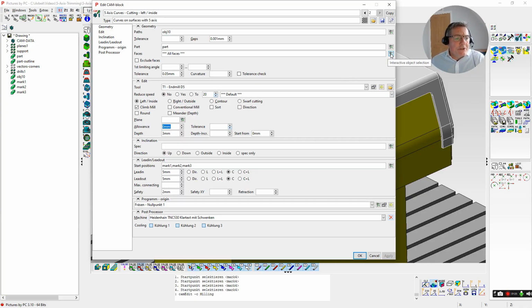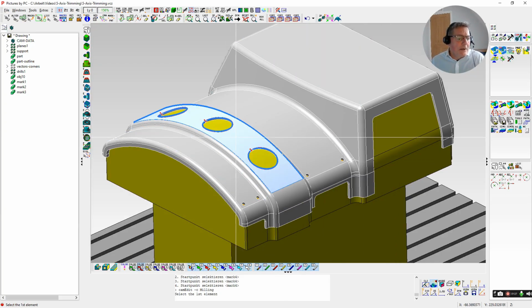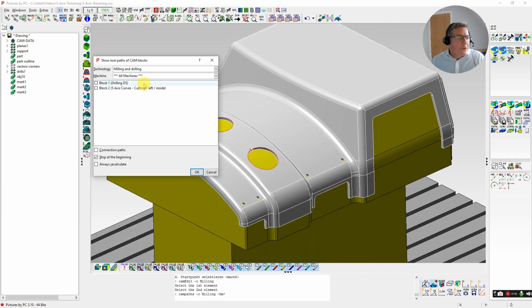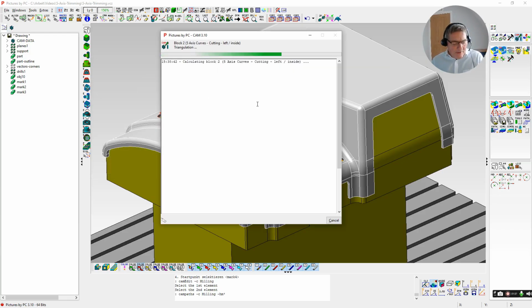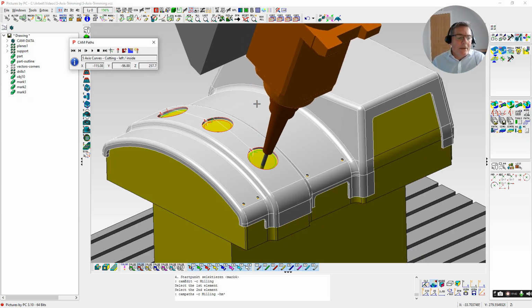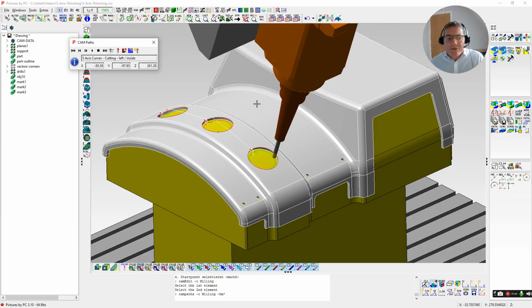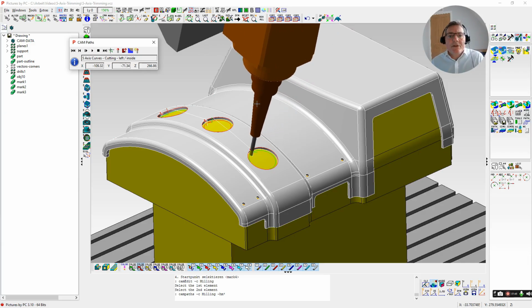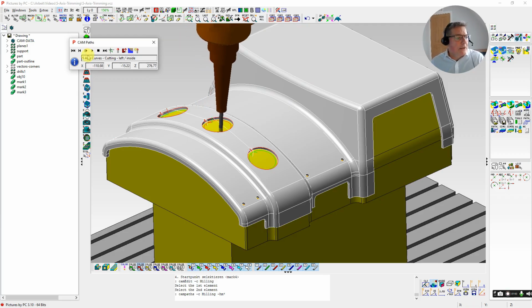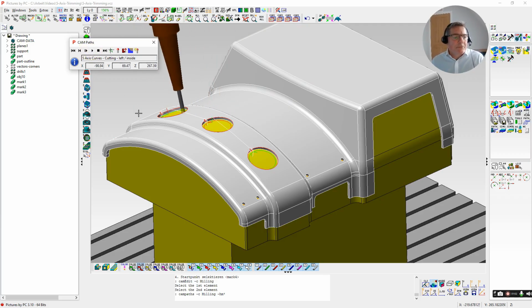The surface selection is the most important part here, because I want to keep the tool orientation perpendicular to this surface, so I select the surface. We run the toolpath. The main advantage of remaining perpendicular to the surface here with 5-axis is that we can maintain tighter machining tolerances and improve the surface finish compared to 3-axis pre-positioned operations. So that's the first 5-axis simultaneous machining.